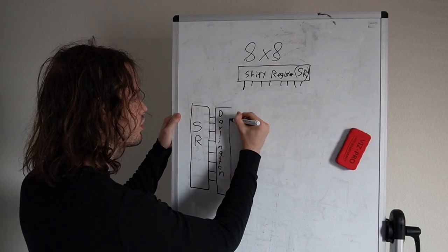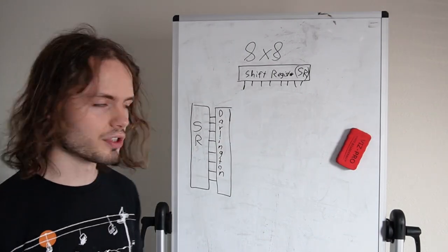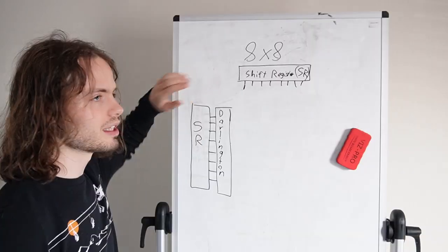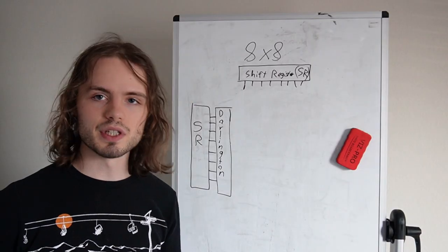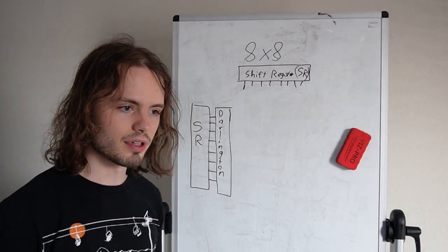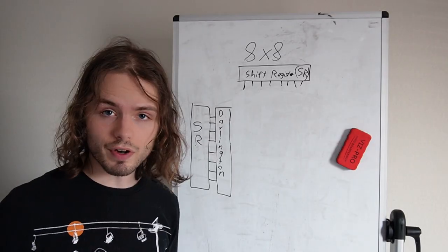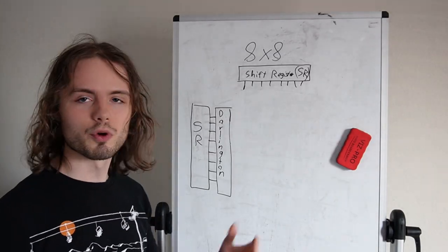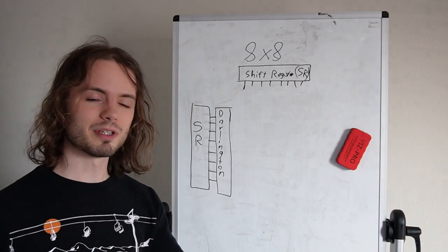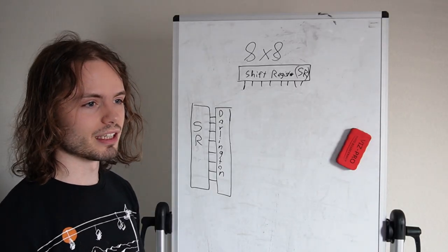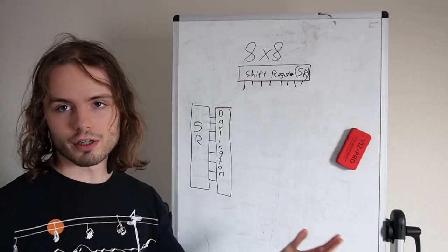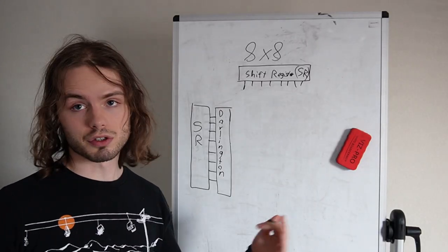And to explain why I made the choices, one is the registers lets us remove the need to individually drive every LED with a GPIO or a buffer. For an 8x8 array, that's 64 LEDs. That's way more than the ESP32 has. And I'd rather not buy a microcontroller with a lot more GPIOs just to do that.